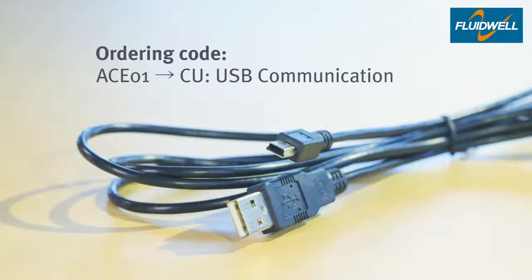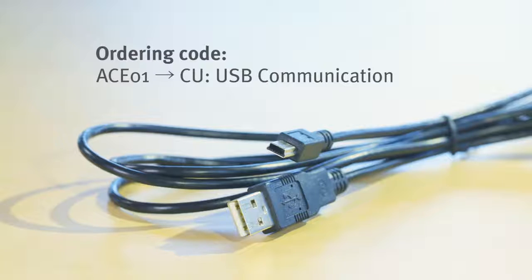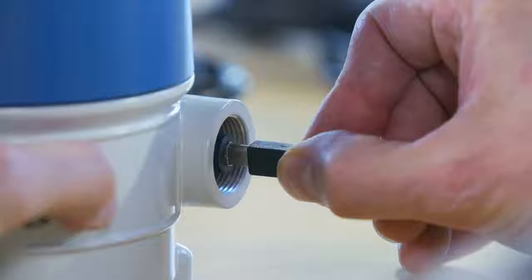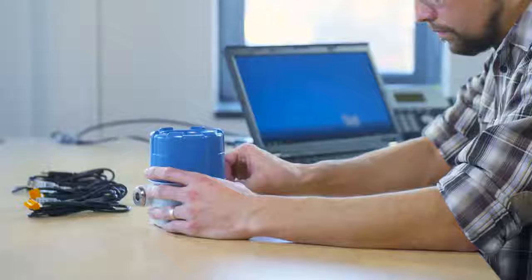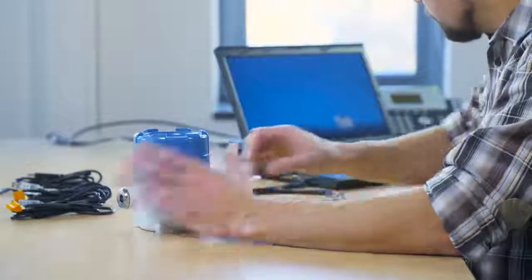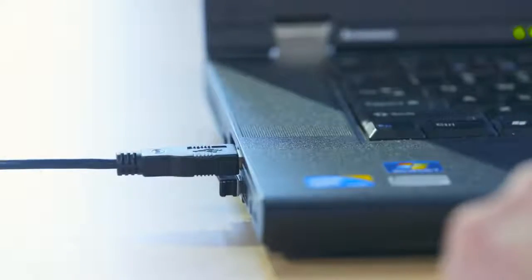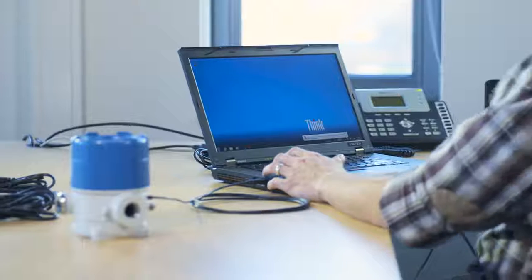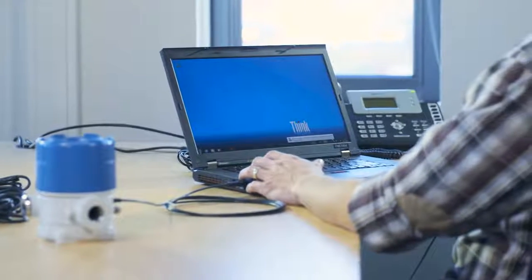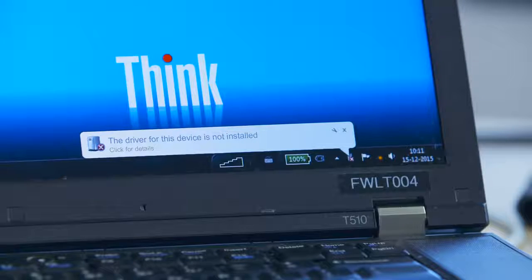The easiest way to connect the E-Series to your PC or laptop is through the USB port. These products come with a mini USB plug on the side entry of the enclosure. After you have connected the cable to your E-Series unit, connect the USB cable to your PC or laptop. You may need to install the special Virtual COM port driver first to use the USB cable.